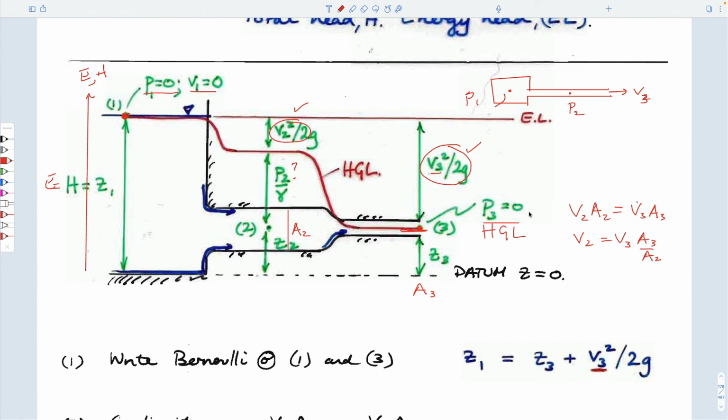And we didn't go through it, but I said it's the same as having a gas cylinder in the lab. You don't tether it properly, it falls over, it knocks the top off, and it acts as a rocket to go through the block wall in your lab and 2 block walls away from you with incredible energy. So this is an analog for that. A closed volume with a given pressure inside it. We said it doesn't satisfy Bernoulli strictly because it's not steady state.